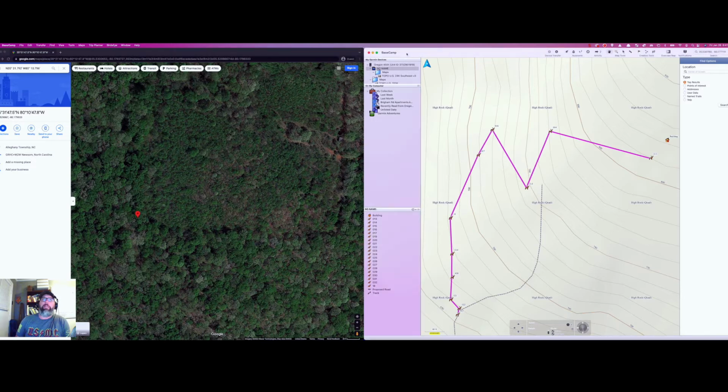But this is what I use. I use this Garmin Basecamp, and this is free software with Garmin. Now, the contour lines I have right here are there because I have a map installed on my Garmin GPS, and it is the 24K of the Southeast, and that gave me the level of detail that I needed to be able to lay these points out. Before I ever got out there, I was able to measure these through here and pinpoint them, and already knew how far it was between the waypoints and what my elevation gain was because of the contours. Each line represents 10 feet in elevation gain.